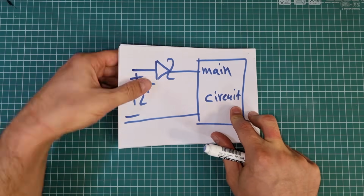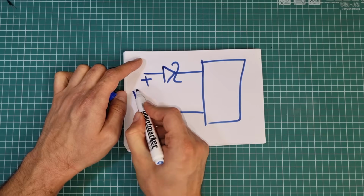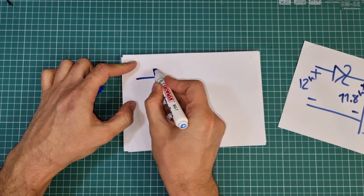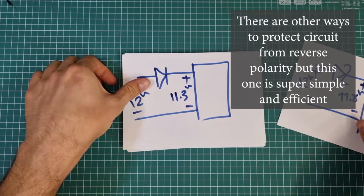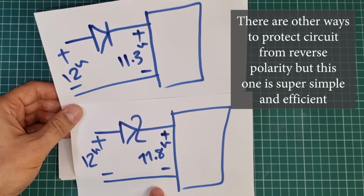You may ask why a Schottky diode is used here. Because a Schottky diode drops a very low portion of the input voltage, for example 0.2 volts. If you use an ordinary diode here, it will drop around 0.7 volts of the power supply. But Schottky diodes drop only 0.2 volts.